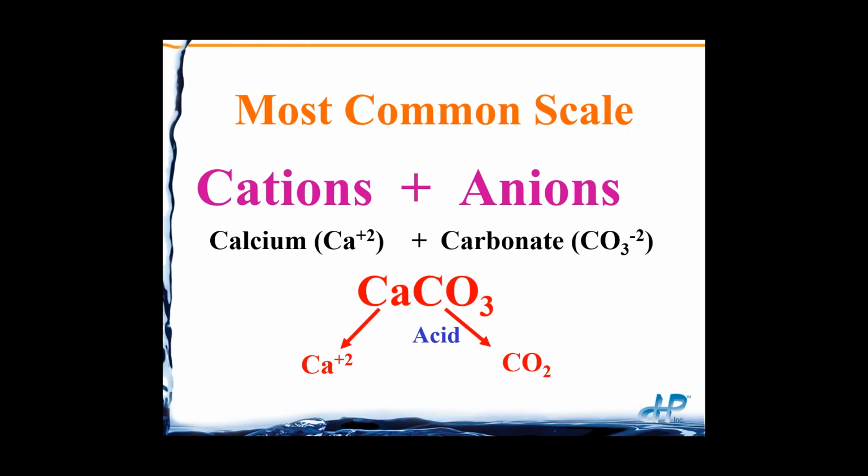Just had a client just last week that had to throw away elements because they were so plugged up they couldn't get any cleaning solution to go in. Now, they removed and replaced them, but the elements are still around. We're going to see if we can soak them and get them dissolved, because carbonate is going to dissolve readily when we put it into contact with acid.